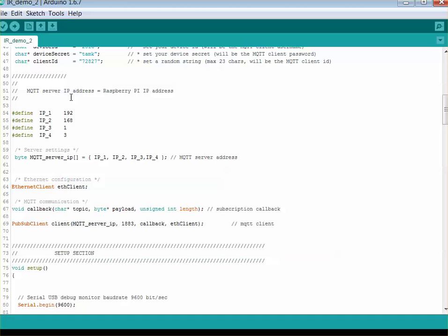If possible, it's recommended that you use fixed IP numbers in the Raspberry Pi, but if you are using dynamic numbers, each time when you boot up the Raspberry Pi, you have to find out the IP number of the Raspberry Pi and change those numbers in this Arduino side program. This is really important to update. And here is the string that we are generating the IP numbers.